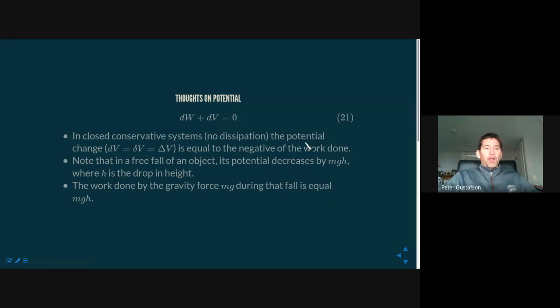If you were to pluck a guitar string, what's going on is it vibrates, and over time, energy is dissipated. It's not all dissipated quickly. It takes some time for that energy to be dissipated. Some of it is lost as viscous dissipation into the air, as it's vibrating and pushing air out of the way. And some of it is lost to changing the temperature of the guitar string itself. This is an internal dissipative activity.